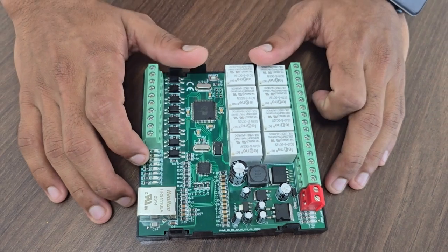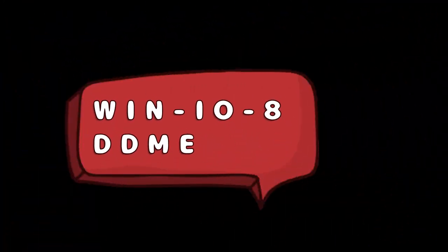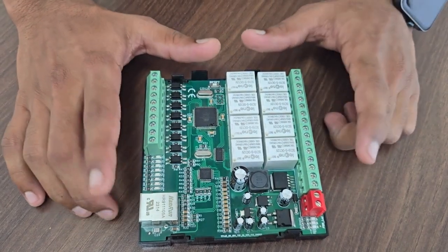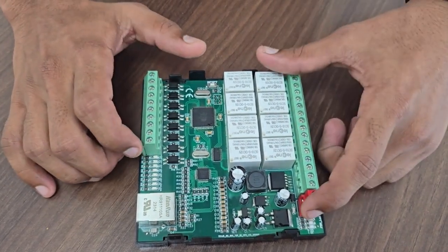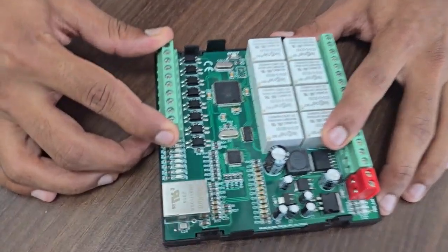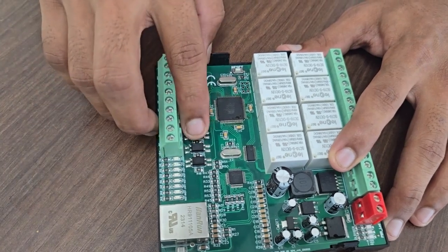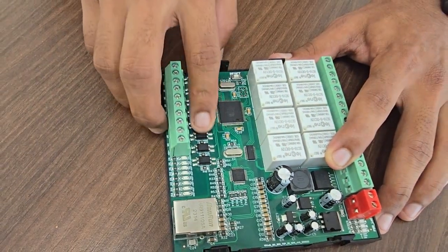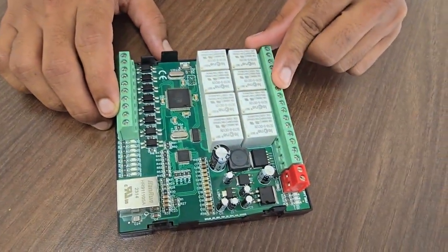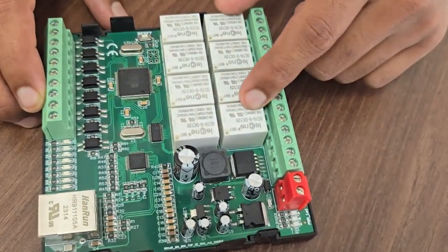Today I am excited to introduce one of our products, ADDME. What is ADDME? ADDME is an 8-channel digital input and digital output board which is operated through relays. These are the digital inputs, which can support 0 to 80 volt input. These are the optocouplers, which support 80 volts, and these are the digital outputs where you can connect any load, which will be operated through the relays.